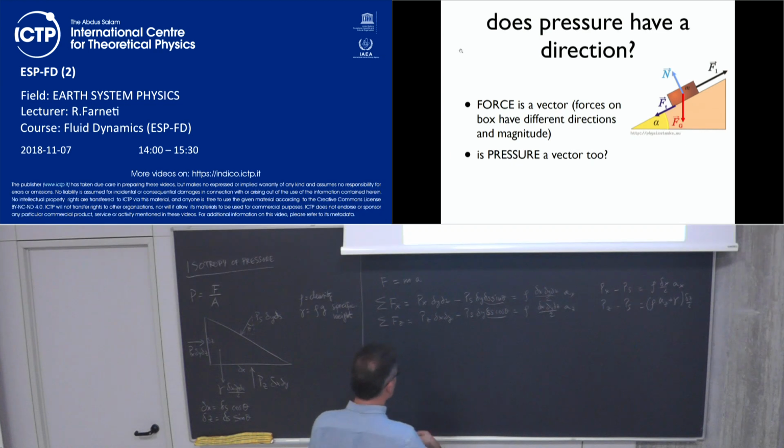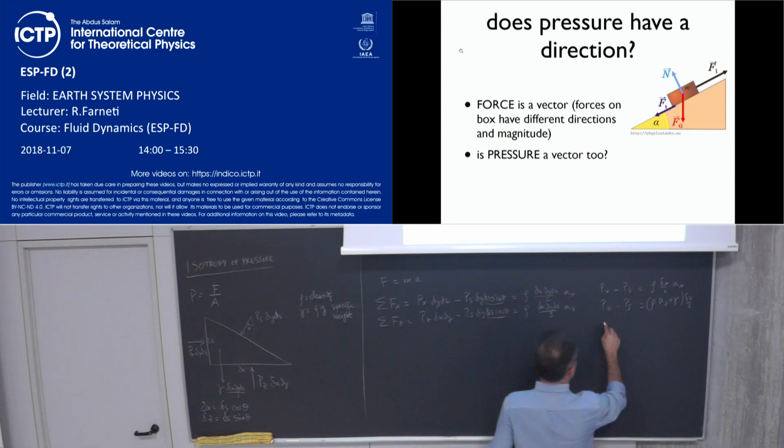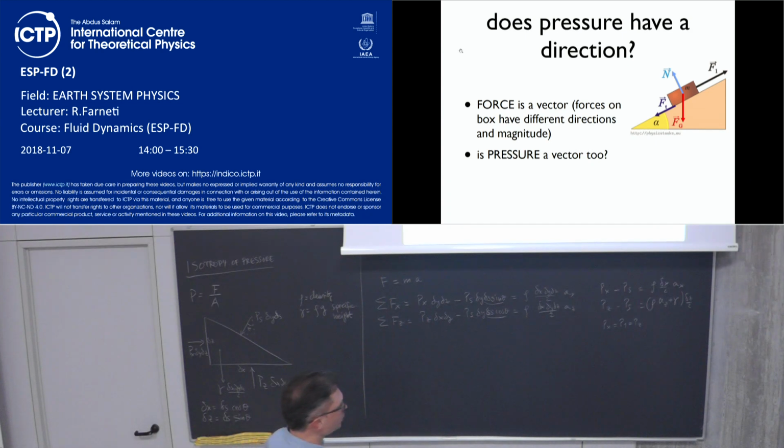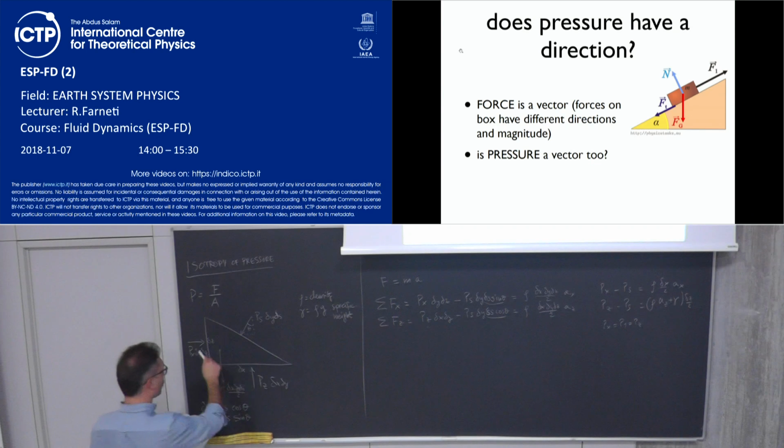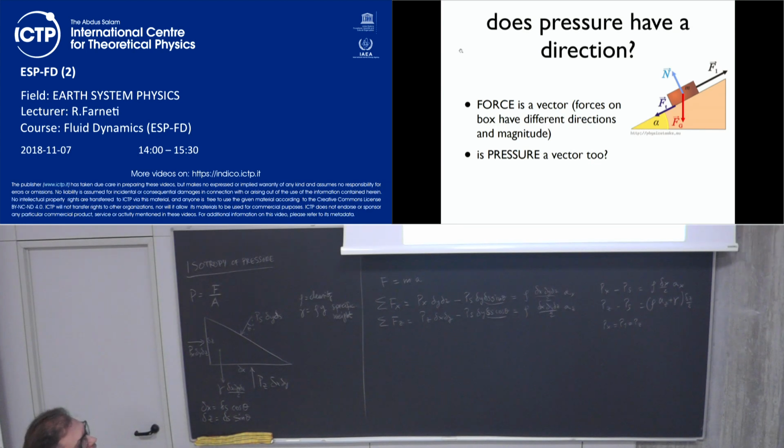So you can make the assumption that as delta x, delta y, and delta z are going to 0, as we're interested in a single point, then trivially this just reduces for an infinitesimally small element of fluid to all the components in the pressure being equal, Px, Py, and Pz. Okay? So all the components of these forces are equal in all directions. So this is true as long as there are no shearing stresses on the surface of the element. Okay?